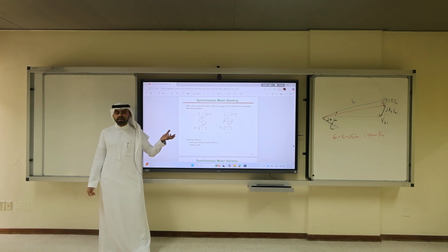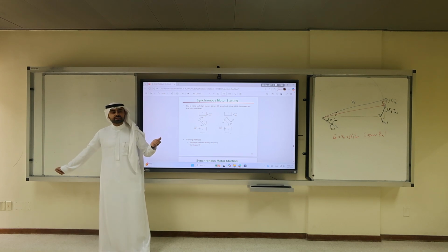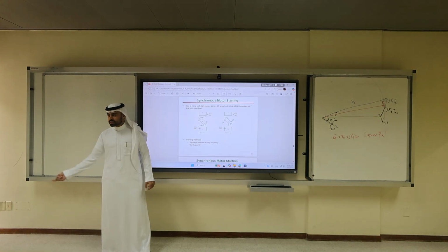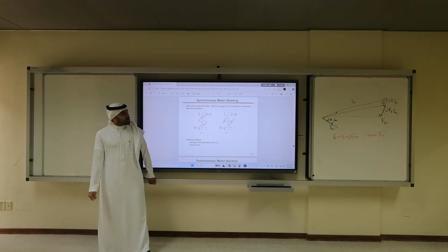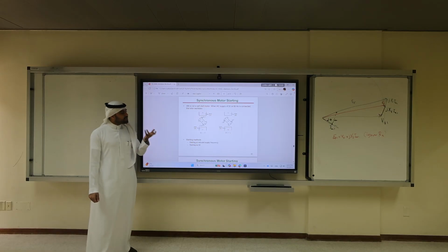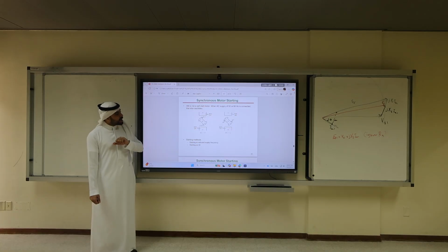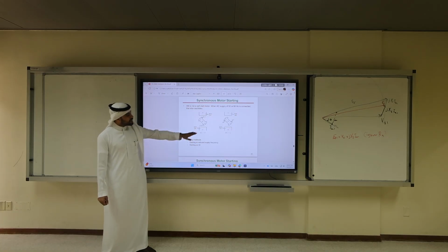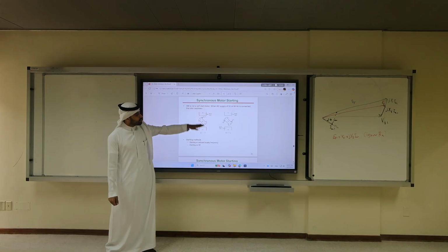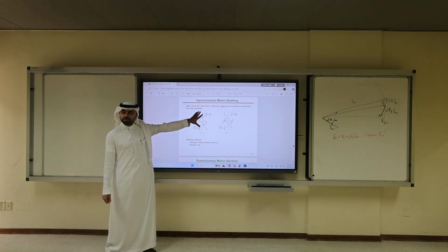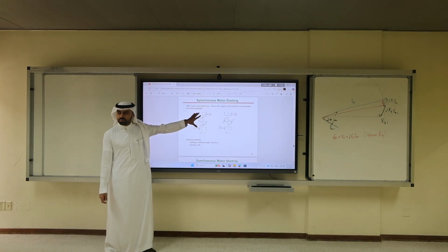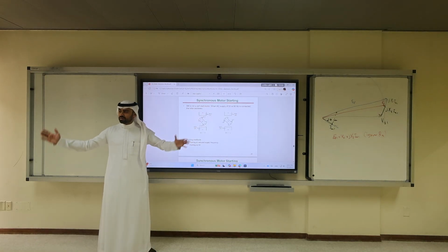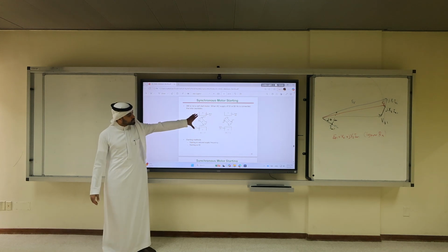Induction machines, the moment you connect them to the plug, they start spinning. DC machines, the same. But for synchronous motors, you cannot. You have to use some techniques. So why is this happening? If we look at the stator poles, north and south, you can have 2, you can have 4. If you have more than 8 poles, something is wrong with your machine because it's going to be too big. And we tend to have small synchronous motors.